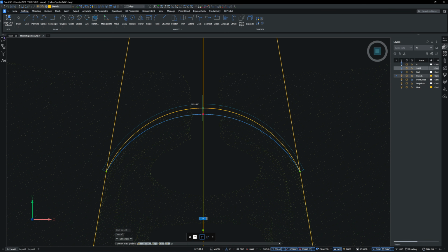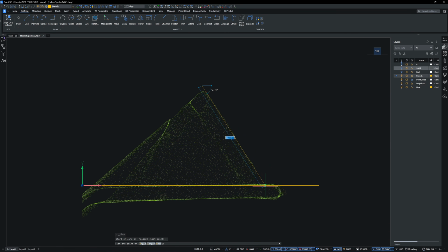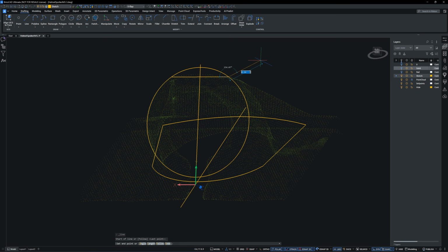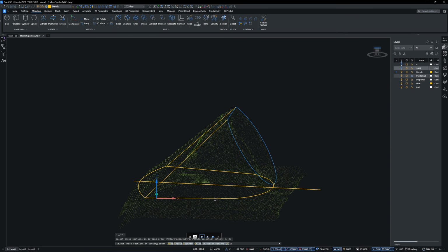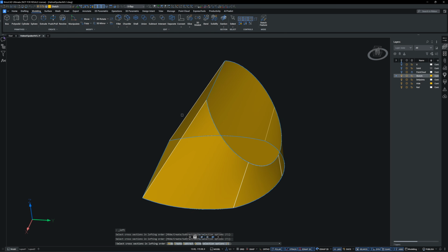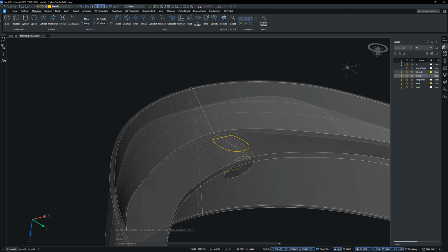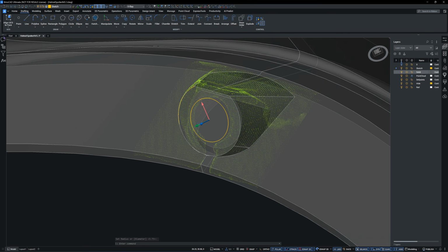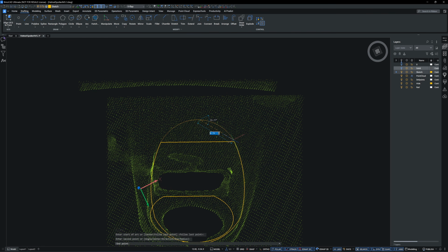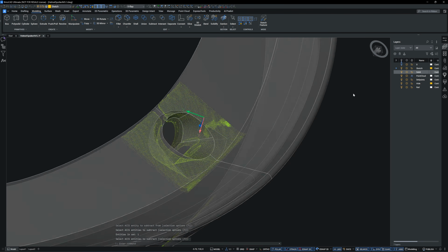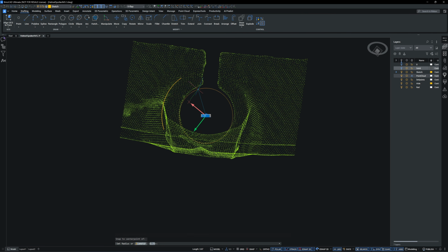Now I'm going to model the housings for the mounting hole. This part is more complicated. I'm creating it as a separate body. Then I will join it into the main one. This loft defines the outer wall, while the inner wall will have a different shape. This is the inner wall, which I will use to cut and hollow out the outer wall.